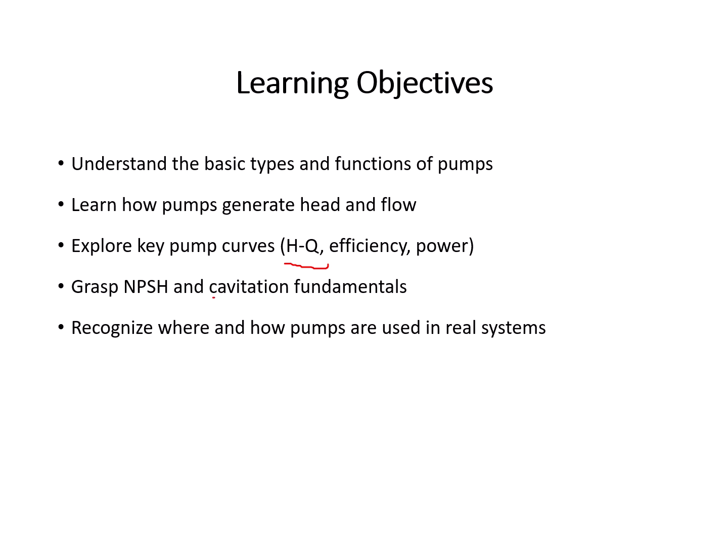We will go through cavitation and the related net positive suction head that will prevent cavitation. Cavitation is a damage and we will describe it later on. So there is a net positive suction head that should be there to ensure that our pump will not be in a risk situation and cavitation will not happen. So these objectives are where theory meets the field and where your understanding becomes practical.